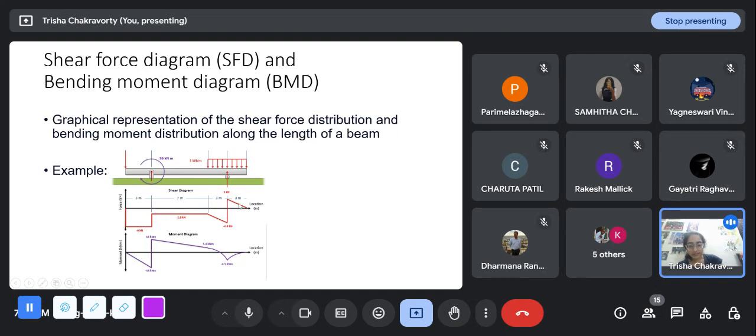If this is my shear force diagram, I tell you to find the shear force at the midpoint. This is the 3733. So the midpoint is somewhere here. If I tell you to find the shear force here, you are just going to come to this point in the diagram, and this is minus 1.8 kilonewton. So this is the shear force at this point, and the bending moment here is a straight line in this region.